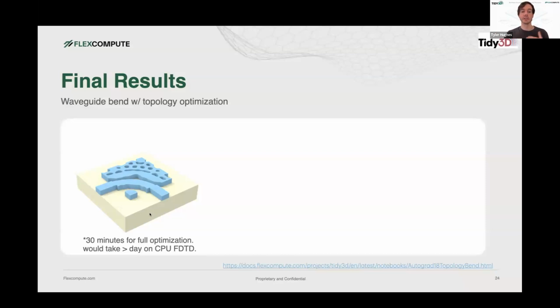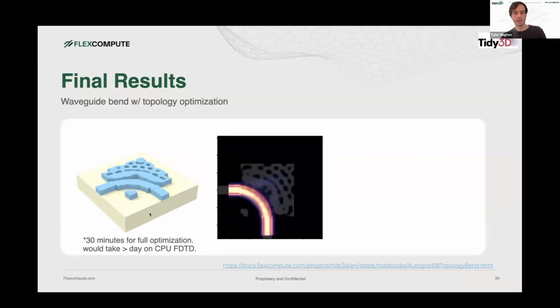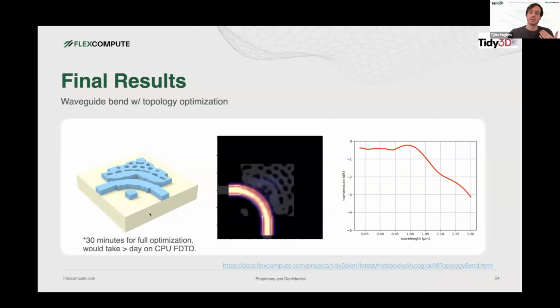So that's quite powerful because it lets you iterate on your design ideas a bit more. You can inspect the intensity pattern. You can see indeed that the light is coupled to the bottom waveguide. And then you can do post-processing or some analysis and look at the spectrum. There are even a lot of tools in the inverse design plugin to do a broadband optimization. So if you really wanted to increase the broadband coupling, you could, let's say, do the average over many frequencies in the simulation.